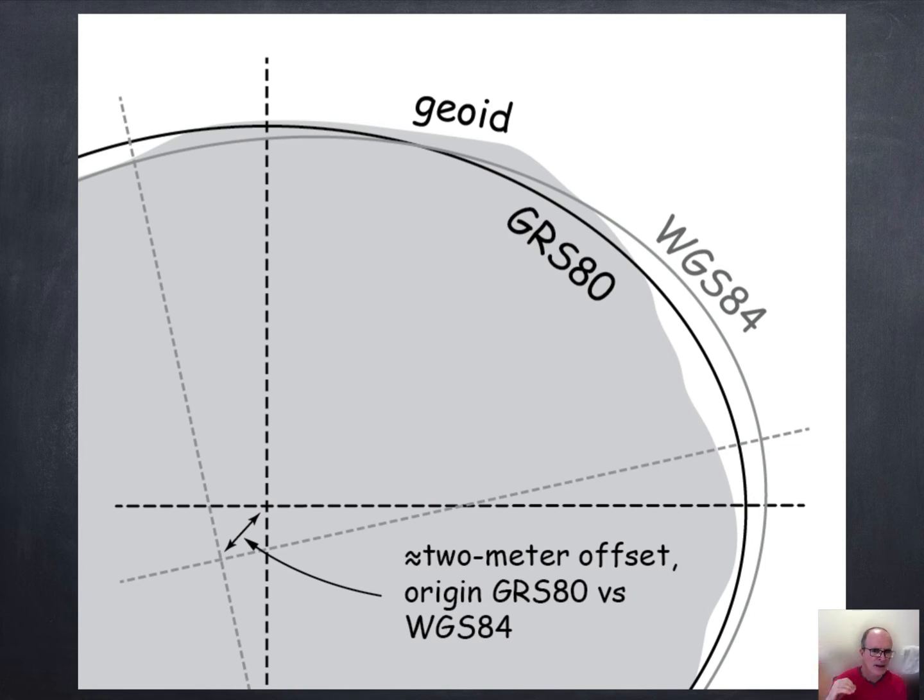We have an ellipsoid that we use in North America, the NAD83 ellipsoid, based on GRS80. And then we have the WGS84/ITRF, an ellipsoid that the rest of the world uses, because the rest of the world adopted their standard after satellite datums were put in place, satellite measurements. Ours was established before, and rather than switch to the new one and cause confusion, because people had measured locations relative to our NAD83 for a bunch of years, we said, well, we're just going to use the old one,